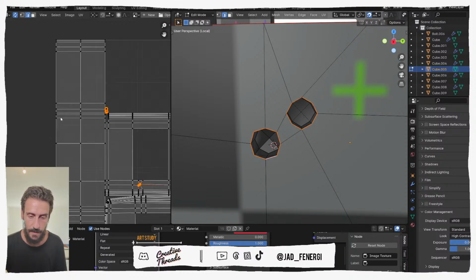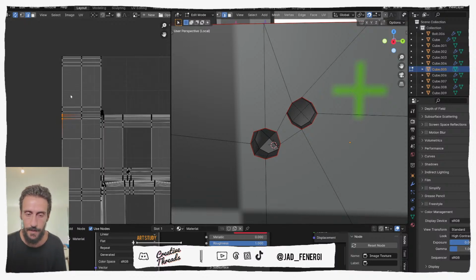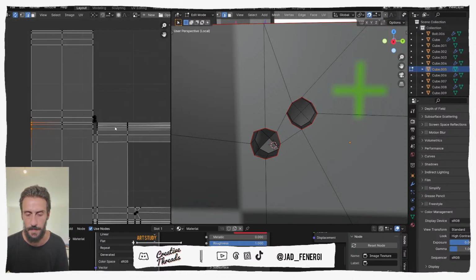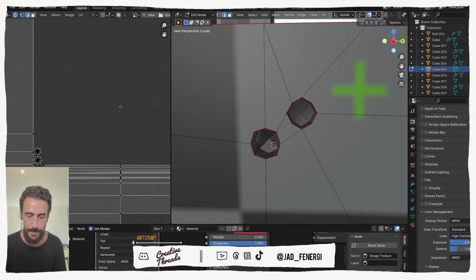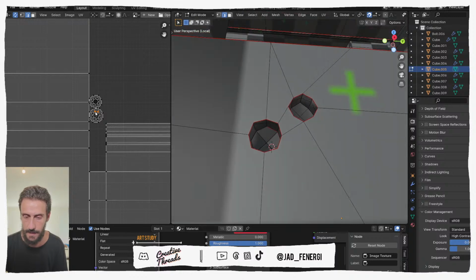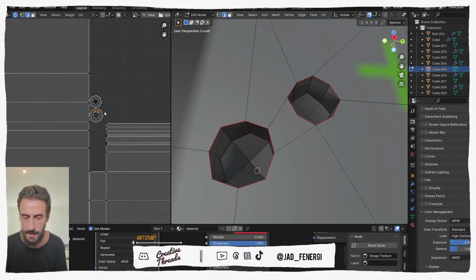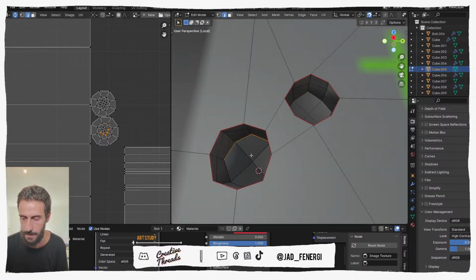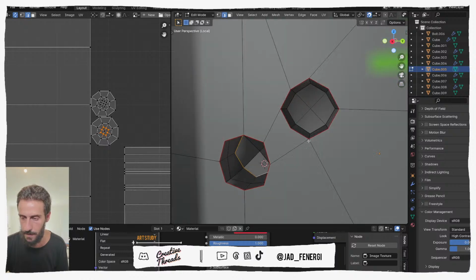If you have something that you've done custom made here, like let's say you have moved some vertices just to fix your geometry or your UVs, you need to right click and pin it, because whenever you unwrap something here, or because you have the live preview unwrapping happening, it's going to unwrap everything again and it's going to remove your work. So now, as you can see, we have all of this presented as these two circles or whatever, cylinders. But what we need to do is also to mark seams in here.